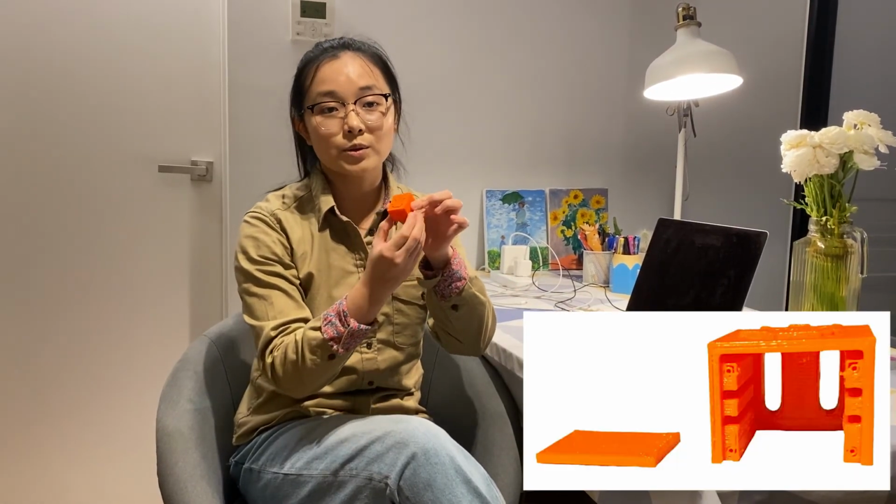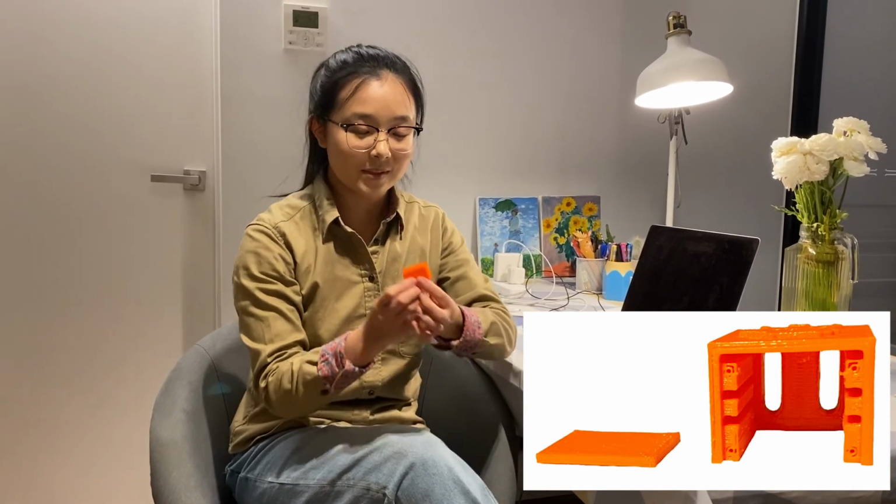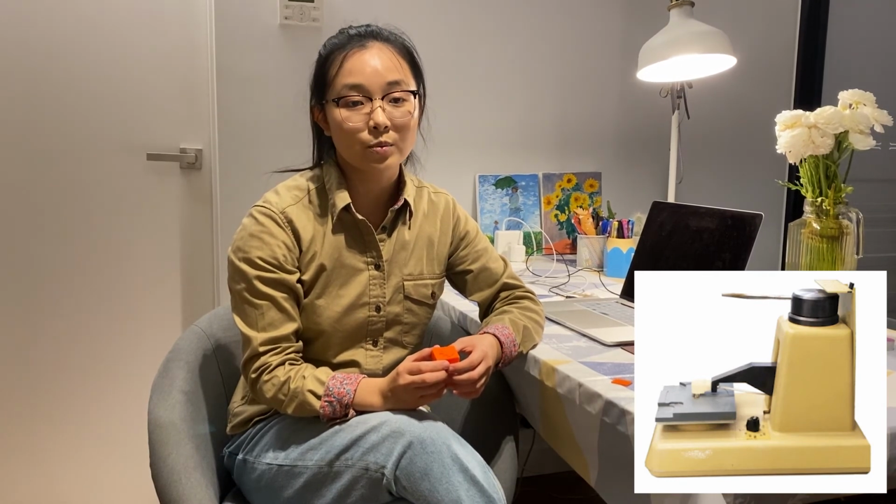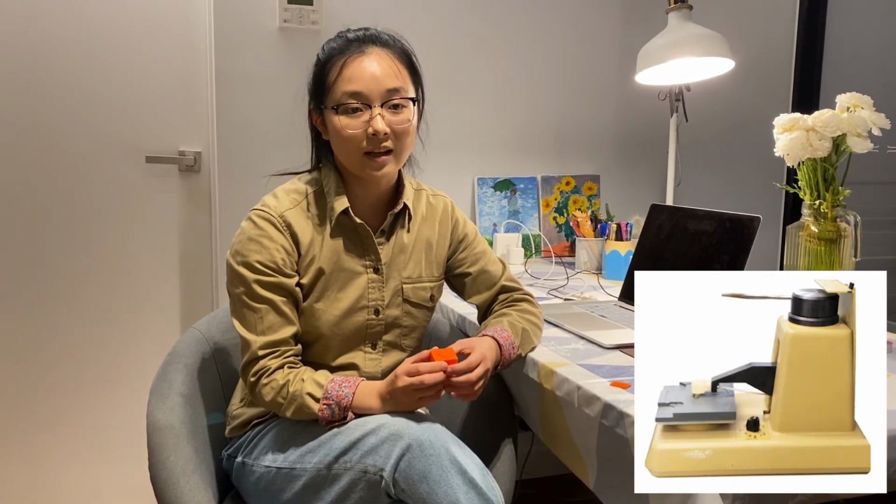To house the Probe PCB, we use 3D printing to fabricate a probe head. It can be installed on the arm of the probe station. The probe head has 3 different height settings for different length probes, and the probe PCB can be easily replaced in case the contact pattern gets changed. When doing the measurements, we operate the probe station to have the probes touch on the wafer contacts.